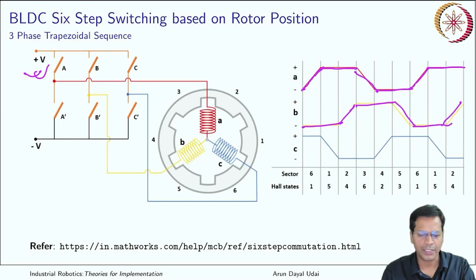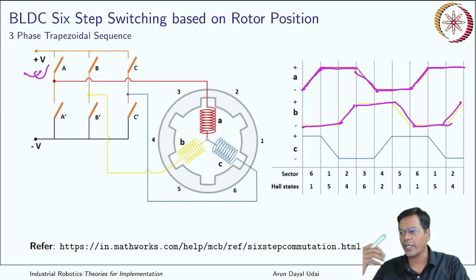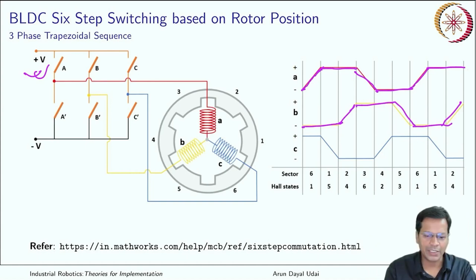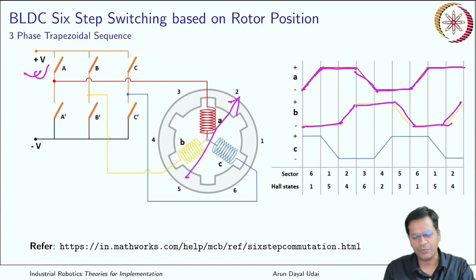So each of these has got 3 phases. The vector sum of all these should be equal to a constant. Okay, that is the constant field, so that keeps on rotating. That creates a rotating magnetic field. If you provide a 3-phase, this is not exactly a constant rotating field. There is a bit of hump because of DC characteristics here. So I hope you got it, how to create a rotating magnetic field.